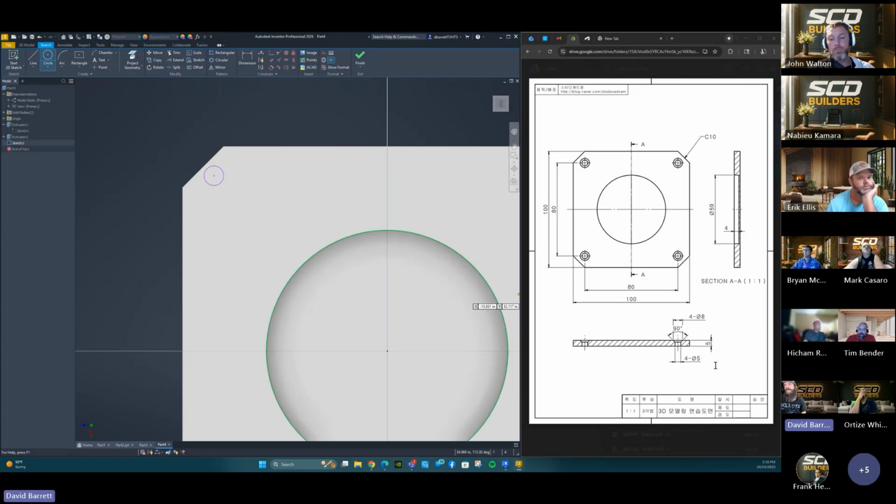It doesn't tell you what size hole to do though. That's the thing. Or does it? Yes, see, 05 is the hole. 08 is the top hole. I think you mean it doesn't show at what point the hole changes shape. So the top hole is 8 and the bottom hole is 5. Yes, exactly. It does the countersink. So it's a countersink at 90 degrees, as you can see. At the top part, it's 8. At the bottom part, it's 5.